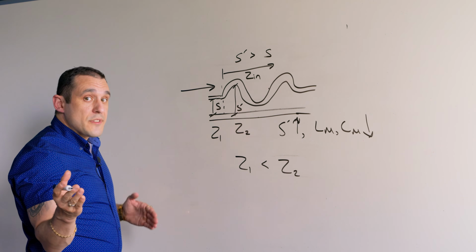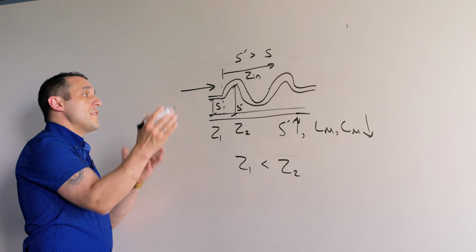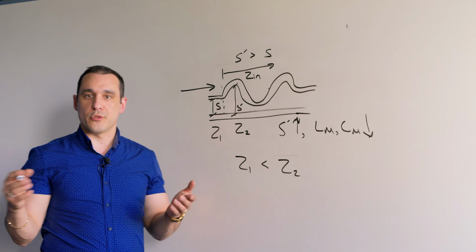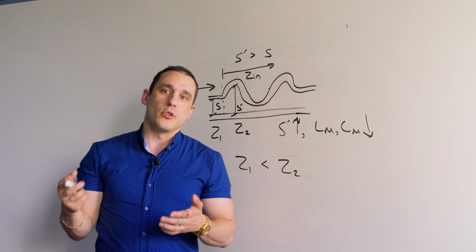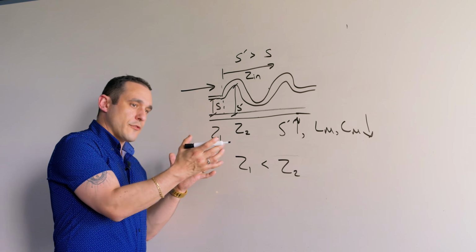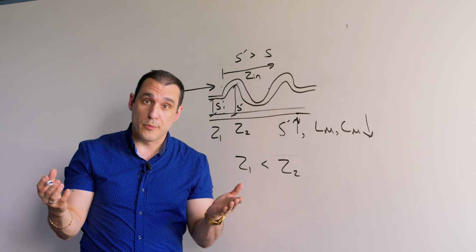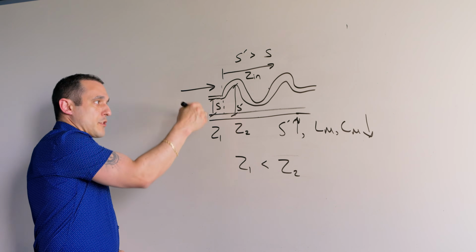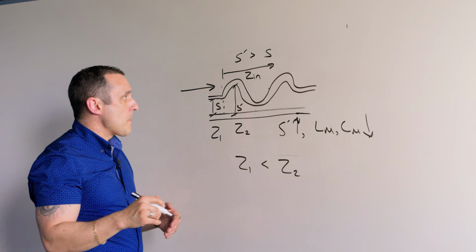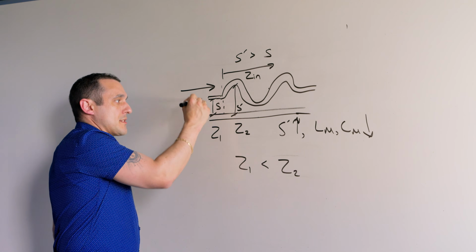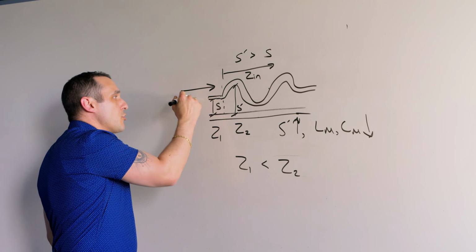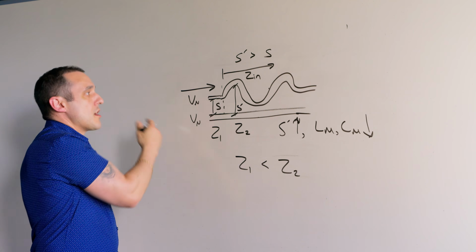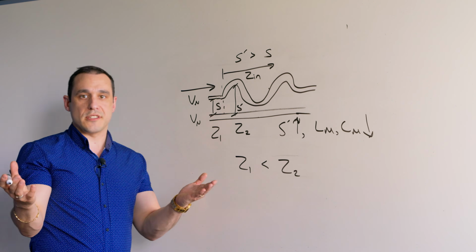Now something else happens that's very important, because these length tuning sections actually create something called mode conversion. So you might be wondering, what is mode conversion? Well, normally when we send a signal along a differential pair, we say it's in the differential mode. And that requires that the signals be equal and opposite polarity, and they're synchronized as they start to enter this length tuning section. But what if I had some noise, let's say some common mode noise, so equal polarity, equal magnitude noise on these traces entering this length tuning section? What happens to that noise?